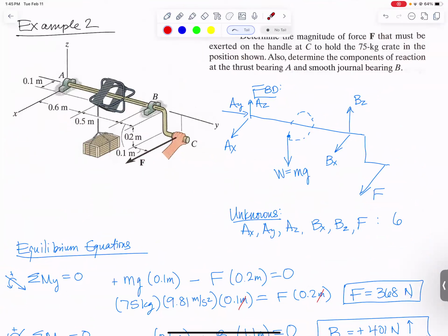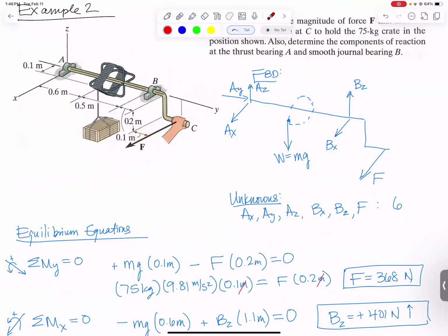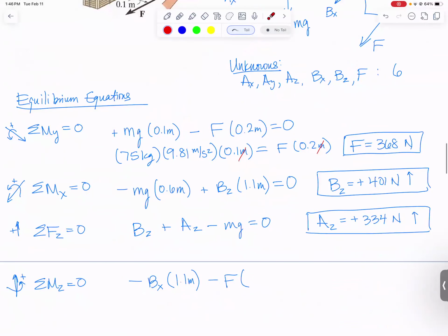So if my Z-axis is right here, and my F is right there, what I need is that total y distance. So I'm going to add up the 0.6, the 0.5, this little 0.1, that gets me to 1.2, and there's another little 0.1, gets me to 1.3. It does not matter for something at the Z-axis how far down below the axis it is in the Z direction. All that matters is from the Z-axis out to F, what is that perpendicular distance? So we're just needing the summation of all those y distances, which is 1.3 meters equals 0.